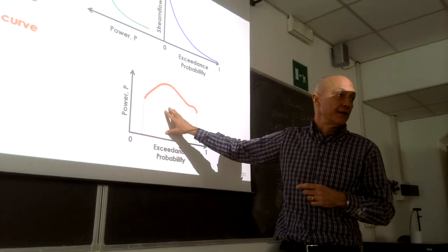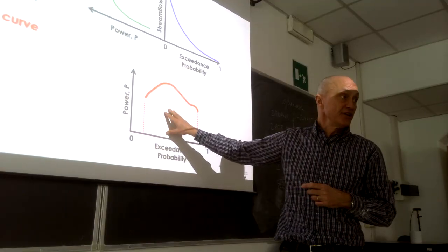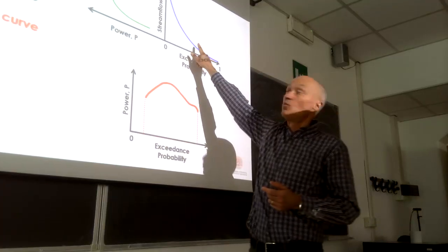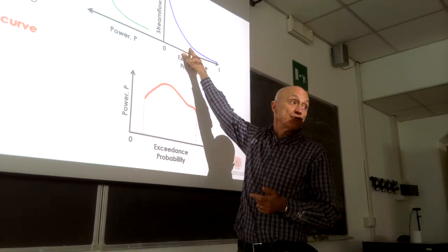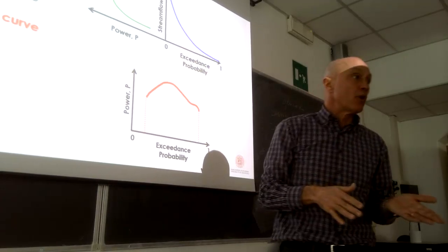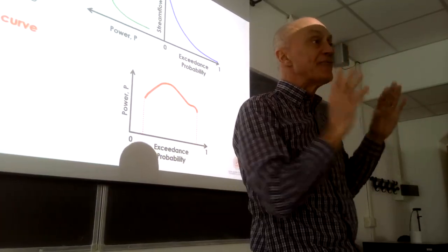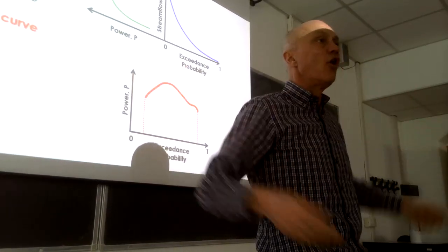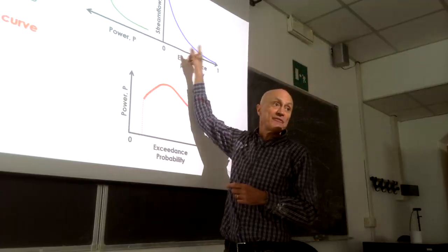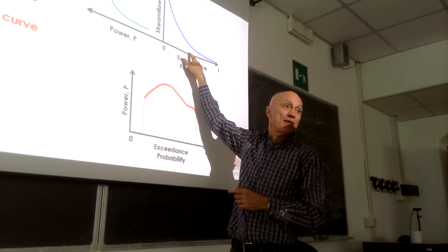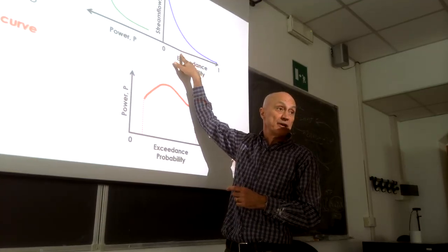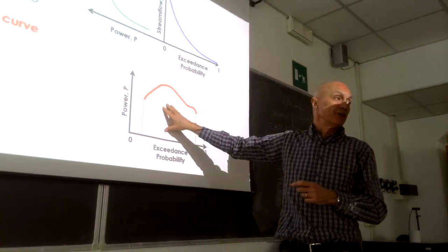Or the flow duration curve is the median annual flow duration curve. So this is a typical year. The area below the curve will be the energy in a typical year with that turbine. You change the turbine, the curve changes, less energy. So you have a graphical representation of the energy in the diagram. It's just the area below this curve.